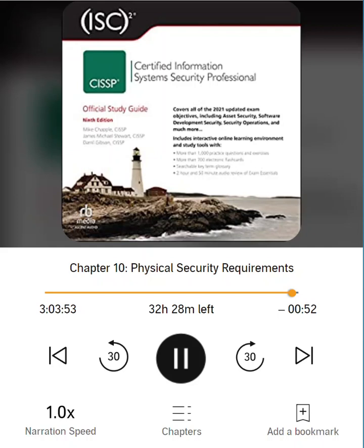Answer D. A capacitance motion detector senses changes in the electrical or magnetic field surrounding a monitored object. A wave pattern motion detector transmits a consistent low ultrasonic or high microwave frequency signal into a monitored area and monitors for significant or meaningful changes or disturbances in the reflected pattern.